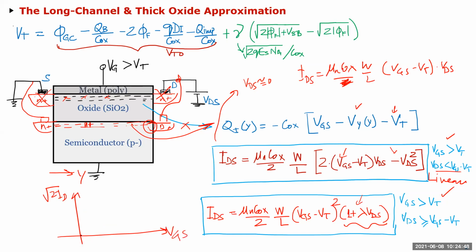We saw that it was kind of like that. It wasn't really linear, and it wasn't really intercepting. So it was true for this small region. And then once the field got higher, you saw that it deviated away from our equation. And when it got lower, at low field, this is called the weak inversion region, which we haven't talked about, and I'll talk about it very briefly. Weak inversion is called the subthreshold region of operation.